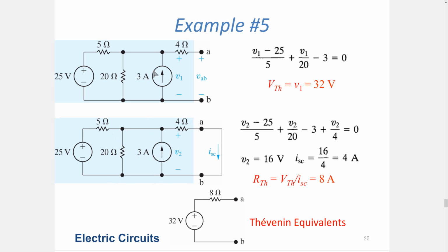And I have a fourth component because I have short circuited the circuit. I have another current flowing, V2/4 ohm, equals 0. Now, if you take a look at this, I have one unknown and one equation, so I can solve it. If you do the math, you are going to obtain 16 volts, as you can see here.